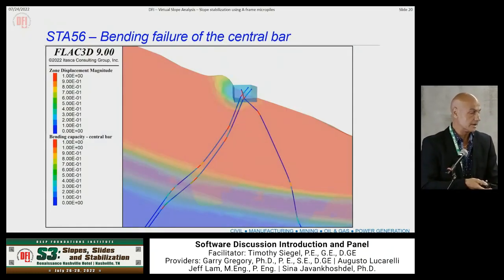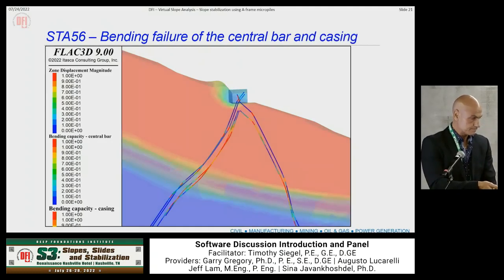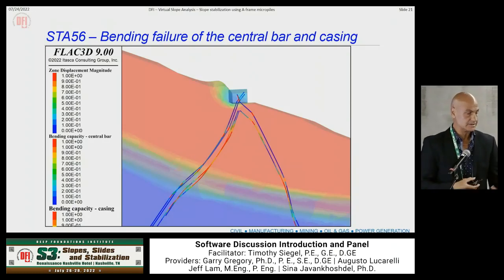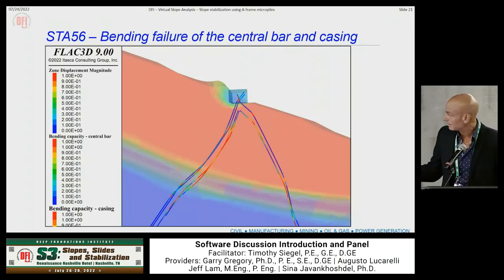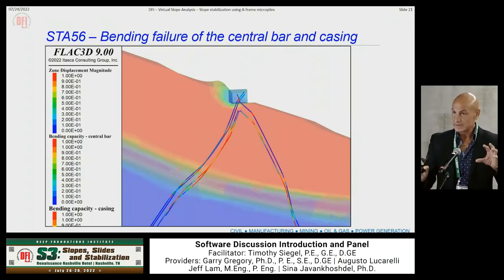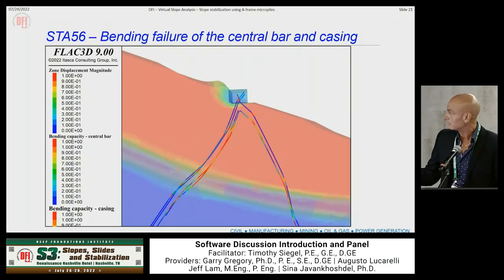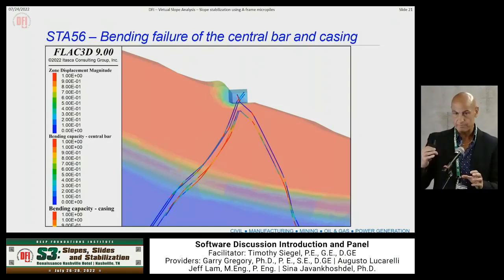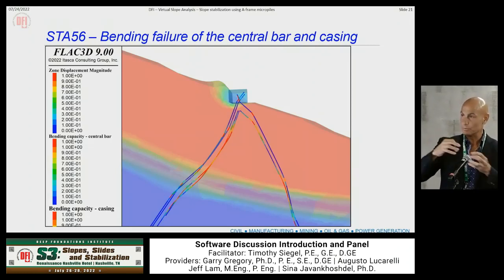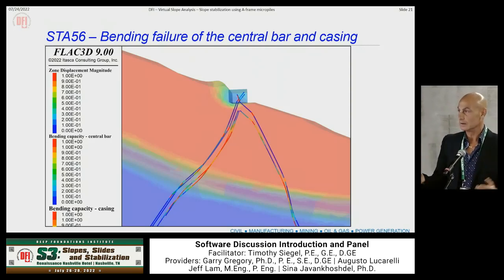So this is just a detail of the potential passive wedge that would form. The bending failure, then, is how the system would fail. Obviously, in this case, we're going to get into more detail a little bit later, but you see that there is a bend forming inside the capping beam. That is the connection of the plate and the rebar. So the kinematic of the capping beam, the rotation, imposes too much stress, theoretically, to the connection of the plate and the rebar. So once the rebar fails inside the capping beam, we don't have enough transfer with the casing, and then the system becomes essentially labile, like having a hinge connection instead of having a fixed connection at that point, and you lose a significant amount of stiffness. It could still be stable theoretically, but the amount of displacement would increase so much that you would go out of service limit state. So this is the detail that I was talking about earlier.